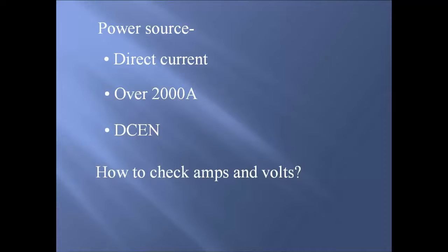How to check the amps and voltage? For volts, you must look for the certified sticker on the machine. This certifies that the machine gauge is accurate. Remember, the certification date should not be older than 1 year. Then for the amps, check by the welder lead. Use the clamp end of your amp volt meter to get a proper reading.